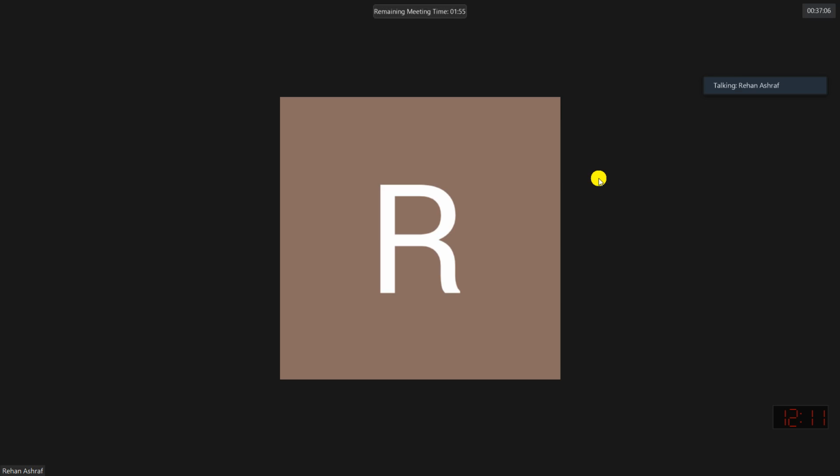Look, basically, the slab load has to go somewhere. It should have supports around it. Now, if you are having nothing on one side or two sides, then you should provide beams on those sides, right? In order to carry the load. Maybe what you were asking is that if for bigger panels of slabs, can we divide it into two panels to economize the slab? Yes, we can do.